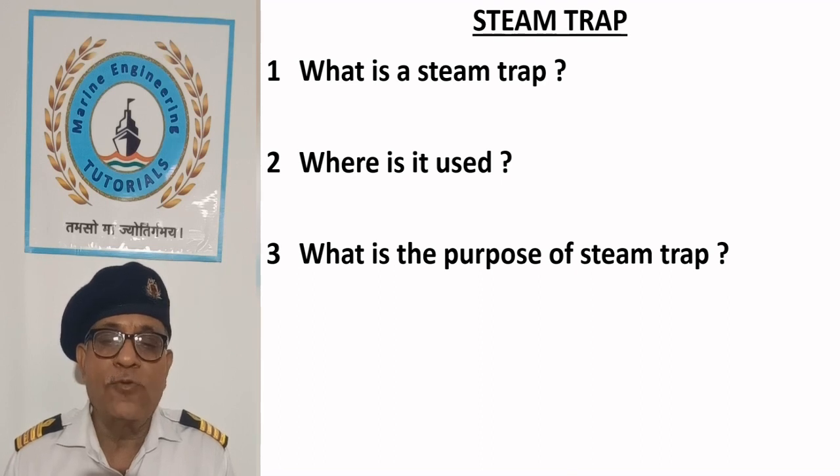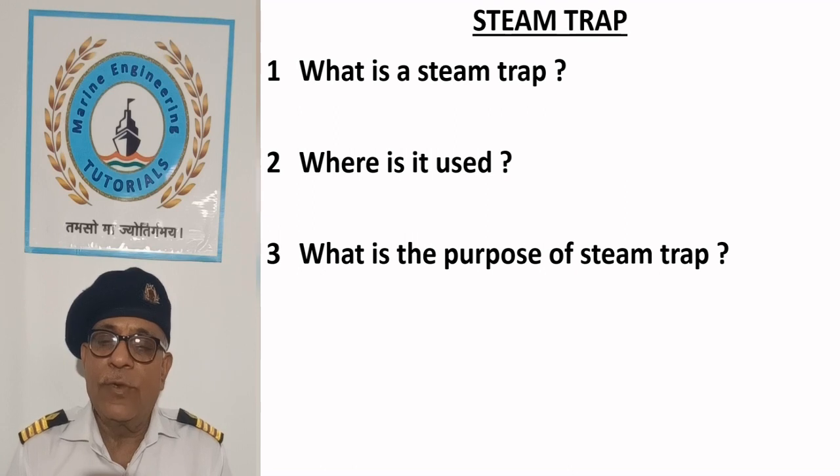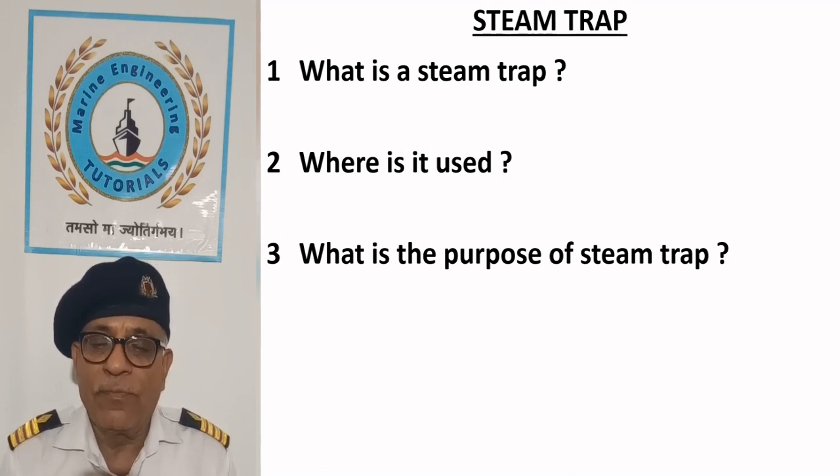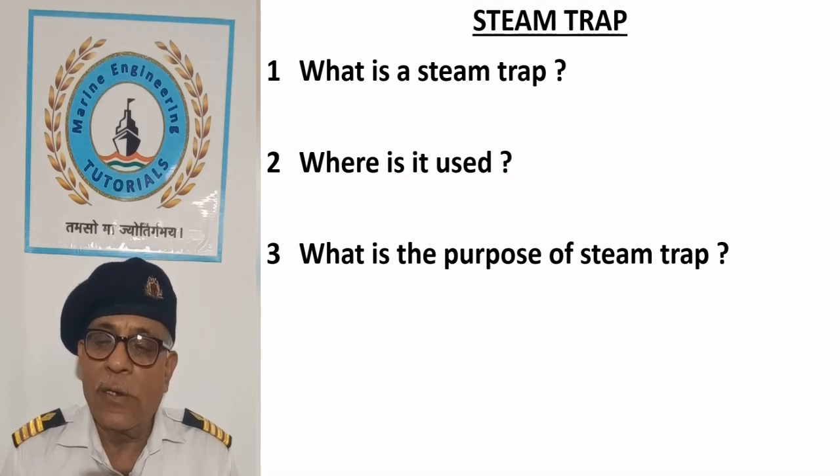What is the purpose of steam trap? The benefit gained with the steam trap is that the steam is contained in the heating coil until it condenses, thus giving up all its latent heat.